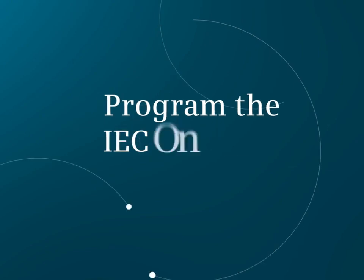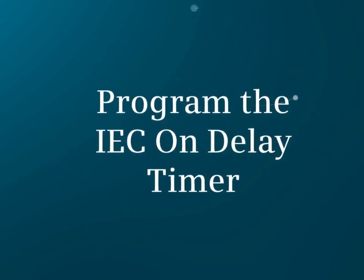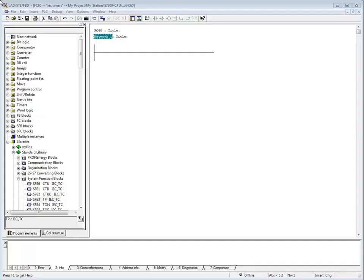In this video, you will see how to program the IEC on-delay timer. The IEC on-delay timer, System Function Block 4, is located in the folder Standard Library and subfolder System Function Blocks. Let's drag SFB4 onto the network.